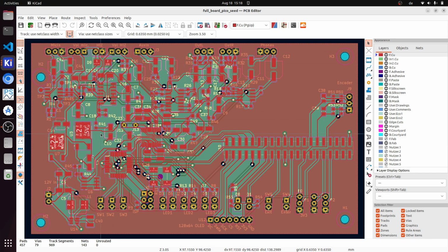By the way, the CS4270 also has the advantage of having all the analog connectors on one side and all the digital ones on the other, and so this made it pretty easy to design it like this, or at least not too difficult. And the power supply is more or less on the left part, situated here. The digital power supply is at the bottom here, just to again try to separate it as much as possible. And another principle I applied is to have all the connectors on the outside of the board.